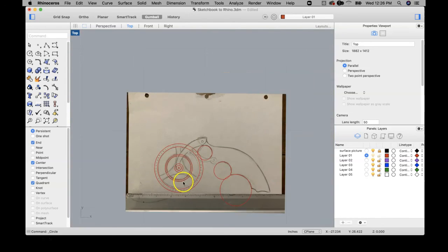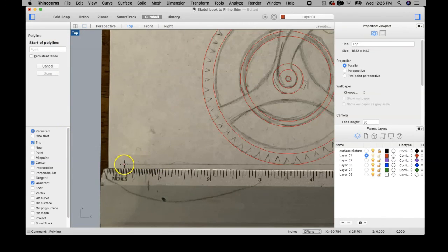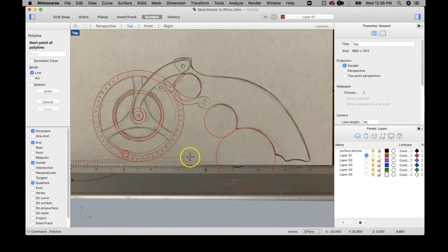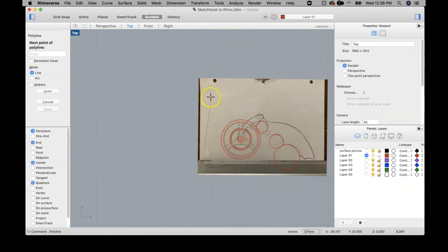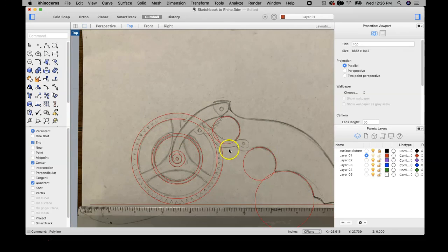Sometimes I'll put in a ground line that represents that line I drew, which is here. I'm going to show you a little trick with this. If I want to hold this line straight, I just hold down shift, and you'll notice it locks it. Shifting for the second point will, if I'm closer to the vertical, lock it vertical. If I'm closer to the horizontal, it'll lock it horizontal. And then I can click there. All right, so now we wind up with what we want.